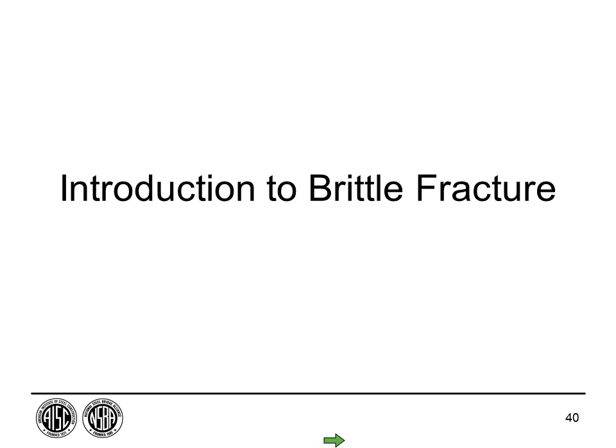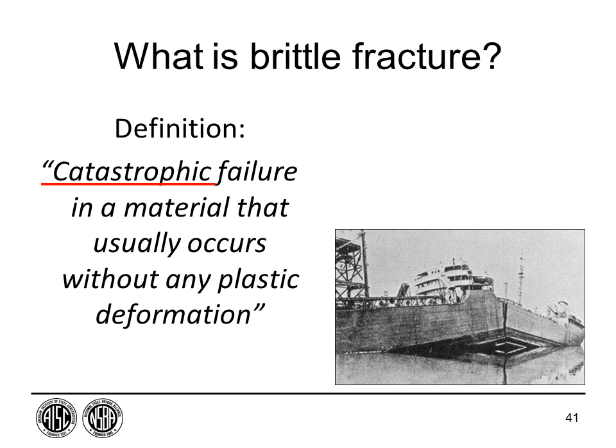We have to differentiate fatigue, though, from brittle fracture. Very often we say fatigue and fracture. They go together like bread and butter, but they're completely different failure modes. And one of the words we always try to call folks' attention to is this word catastrophic. It is a sudden failure that occurs without any plastic deformation. That's a fancy way of saying there's no warning. Plastic deformation is what gives you warning, right? In other classes you've had in steel, when you get yielding or distortion, that's a good thing as compared to something that just breaks suddenly.